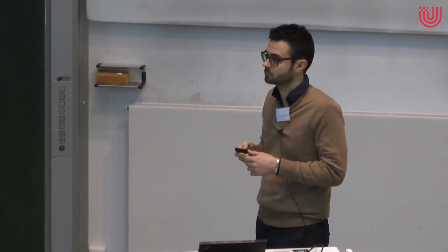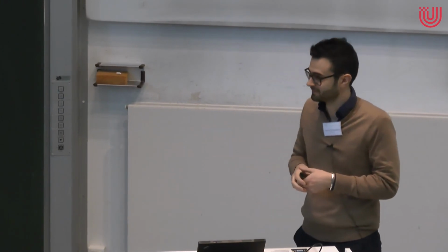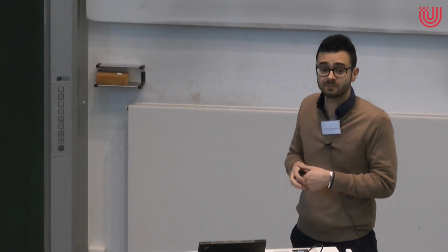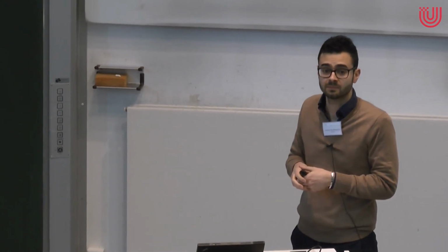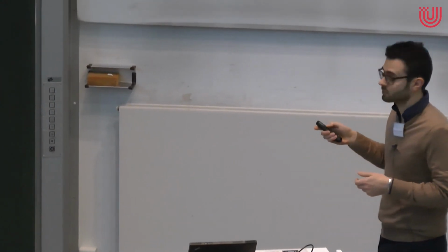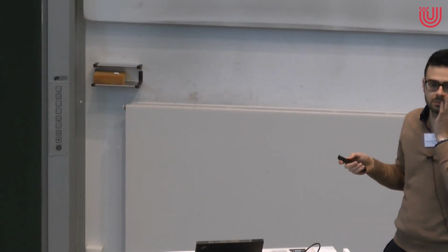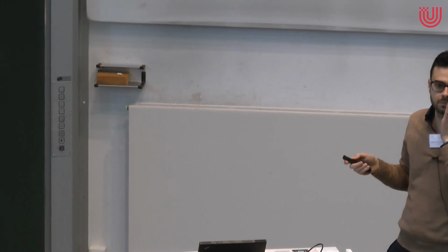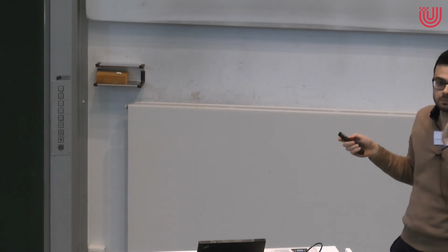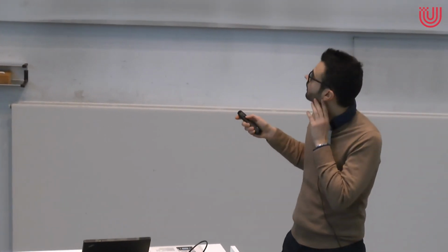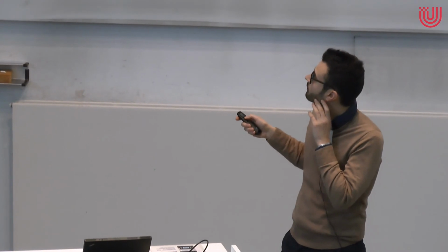Probably a very complex energy consumption model. Did you assume here that you have the baseband processing within the small cell and the remote side for this power? Here in the small cell, you have baseband processing, and the RF output power you consume for the amplifier is different from a micro cell. Here I'm considering a picocell. So according to the type of small cell that you consider, you have a different power consumption model.